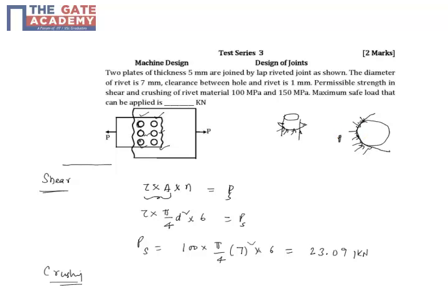So how do you get this crushing load? This is my crushing stress, which is just like a fluid pressure. This stress is multiplied by the overlapped area.